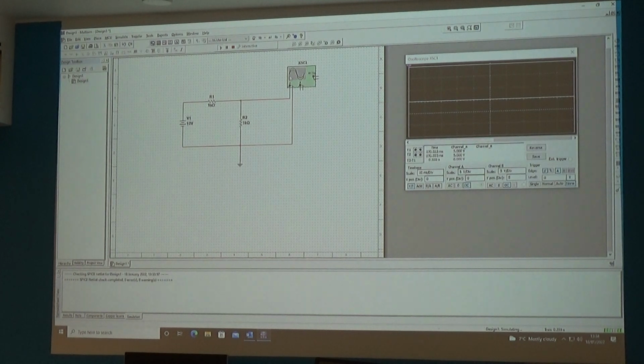If you look down, I'm on channel A. Channel A is 5 volts per vertical division. Look at my cursor. The time scale doesn't matter because it's just a straight line. And now we're using an oscilloscope to be able to do a measurement for us, which is a DC measurement. Okay, I can see, everyone I can see here is doing that absolutely fine, so no problems at all there.